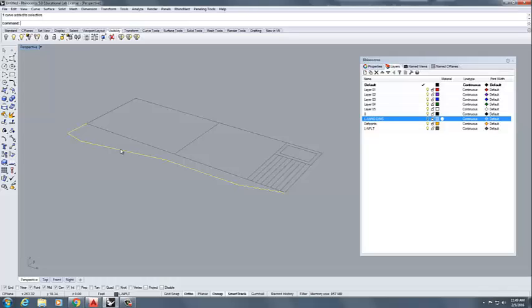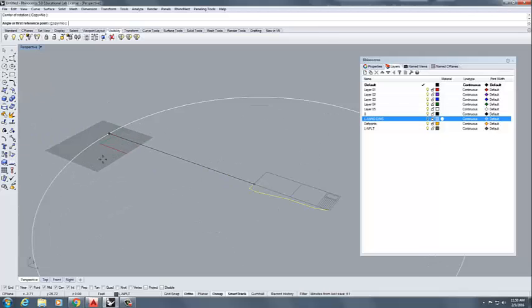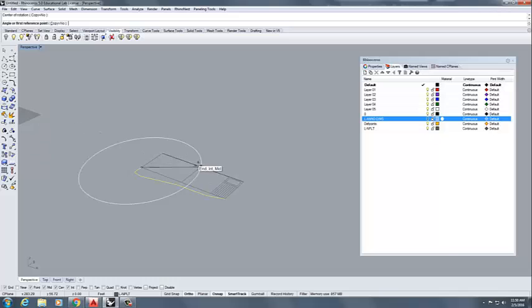I now want to rotate this. I want to just flip it down, right? So that I can extrude it across the pool. I'm going to type rotate, as one might expect. And it says, where is the center of rotation? Well, the center of rotation is this corner right here. But because of the way construction planes work, we are currently set with a construction plane that is, as you can see, visible with this little grid in this direction. So I would just be rotating it in this direction. And my ortho is on, my F8 is clicked on. If I turn F8 off, it rotates the other way. It's no good. That doesn't work for me.